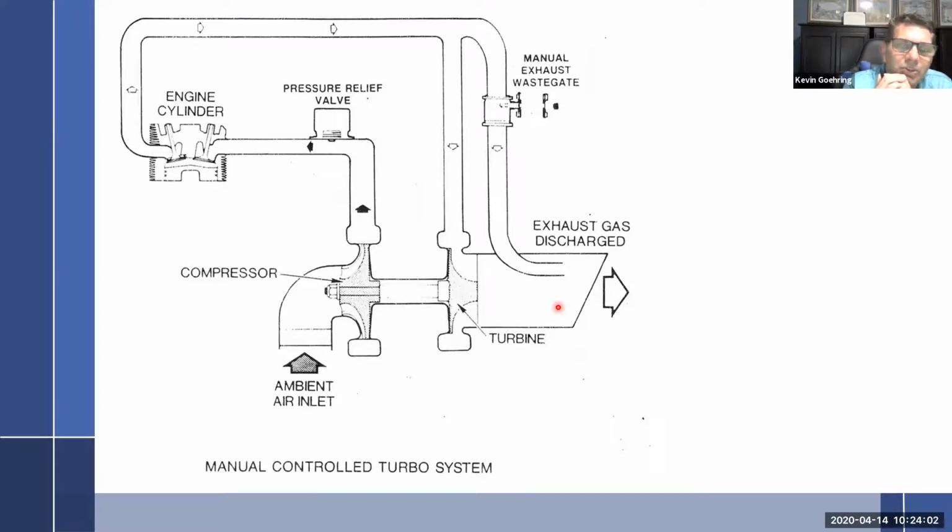Well, simply because you pull back on the throttle, upper deck is going to build up. And because upper deck builds up, all the pressure controllers are saying, wait a minute, we're already at 30 inches. It's at 29 anyway, because you're at ambient. If it's set for 30, it's going to take 1 inch of pressure and go, we're done. We don't need any more. Just go ahead and open up that wastegate. So it takes almost nothing at an idle.